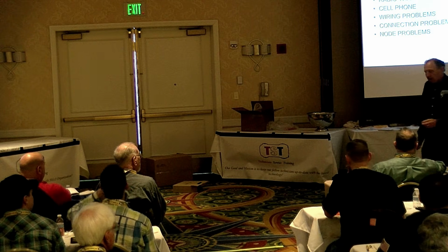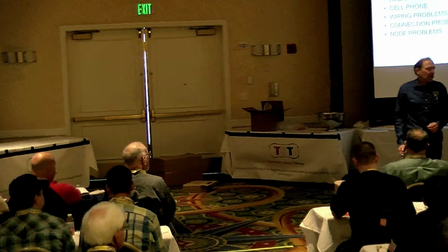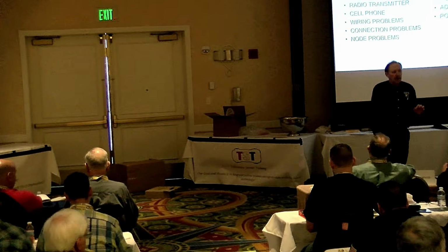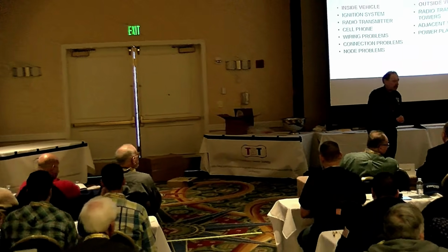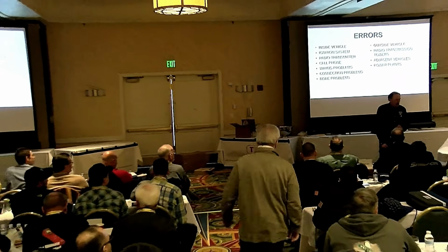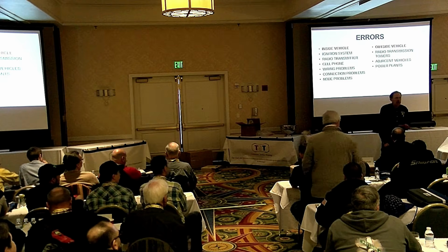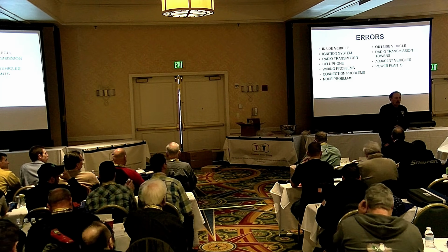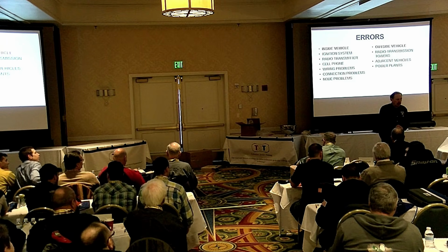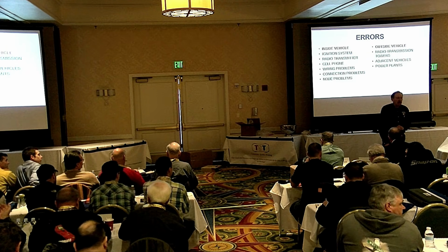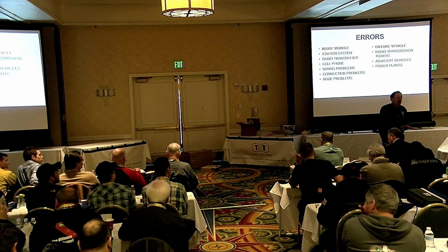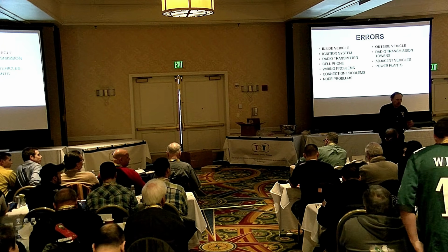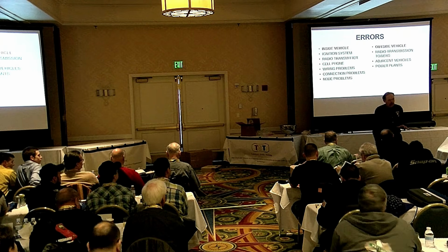So where we're talking about, I had a couple of questions at break I want to clarify real quick, okay? First off, I had a couple of people ask me about synchronous. That means I have a master clock that's in order. In all of these protocols that we covered, these are all asynchronous. They're arbitration, event-style driven. One of the few buses that's in a vehicle today that actually uses a synchronous system with a master clock is FlexRay.